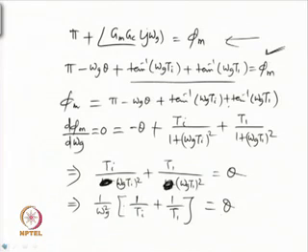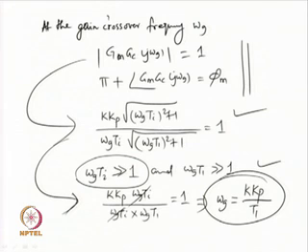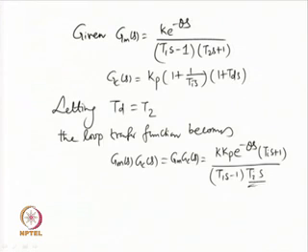Have I forgotten the pi by 2? Because omega T_I is there, this j omega T_I, this is a magnitude coming to the phase angle j omega T_I. So, minus pi by 2 term will come, okay, minus pi by 2, that I have forgotten, because if you write this, the expression for the loop gain will involve j omega_g T_I. Due to this j, minus pi by 2 angle will come.